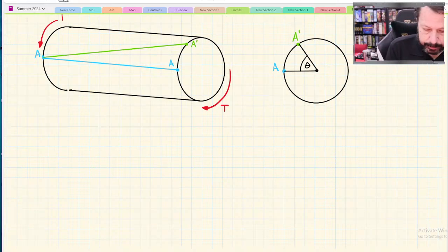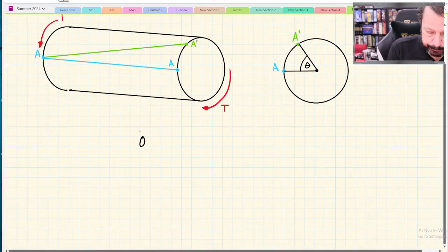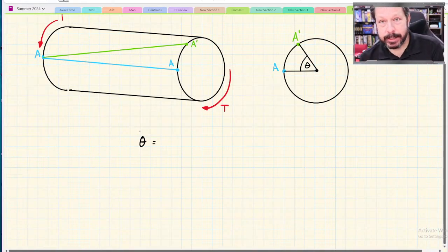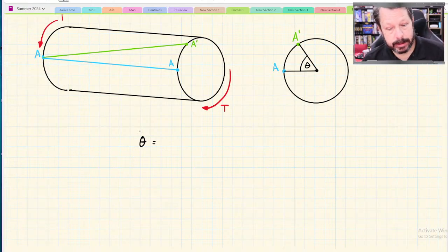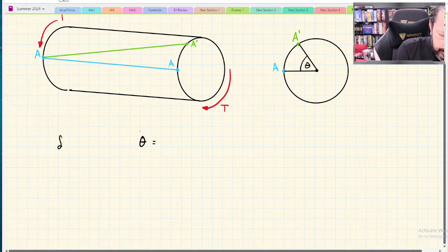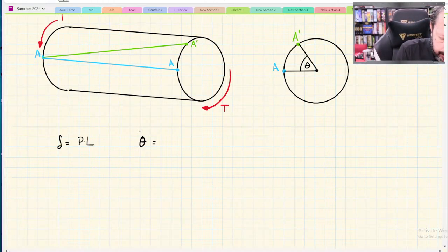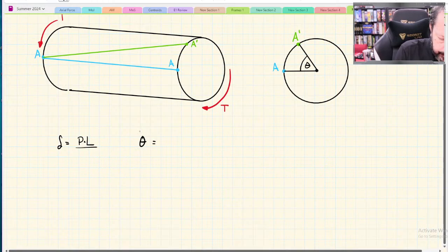So how we calculate this is theta, the angle of twist, equals, and it's very similar to the delta equation. Remember, delta, a change in length, equals P times L over, actually I think we used F. Sometimes we use P, sometimes F. I think in this one we used F, because then it spells FLEA.